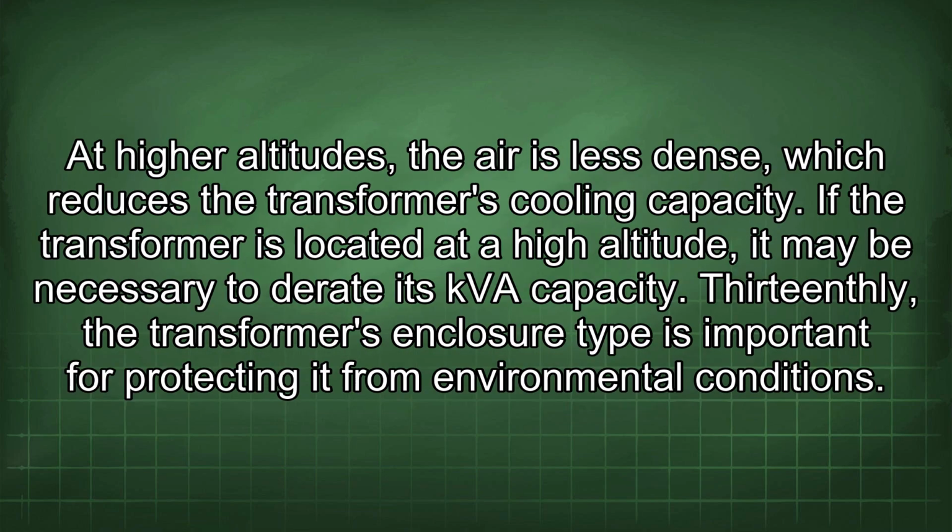Twelfth, consider the transformer's altitude. At higher altitudes, the air is less dense, which reduces the transformer's cooling capacity. If the transformer is located at a high altitude, it may be necessary to derate its kVA capacity.